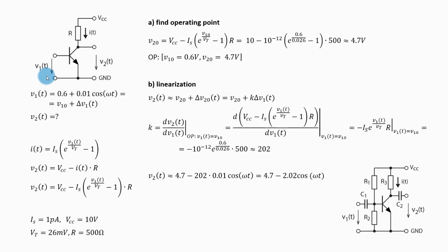Obviously, this is going to be important when you design this type of amplifier, so we often use this type of circuit to set that operating point at the input. We use this voltage divider, which will create some DC value here, and that will set the amplification of this amplifier, and it will even set the DC value at the output.